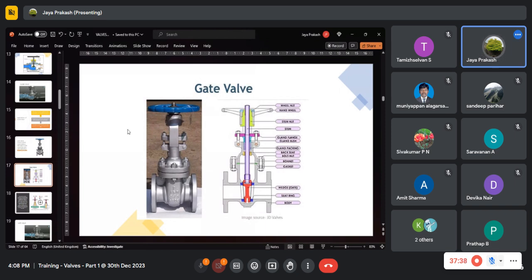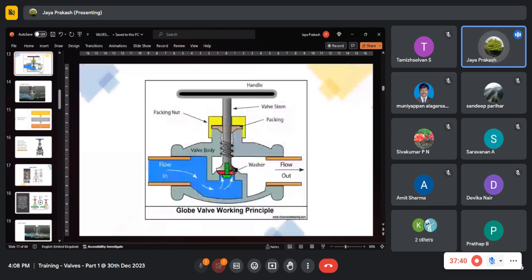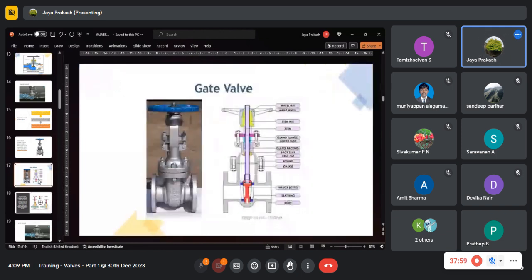They don't go for globe valve. See, globe valve will constrain the pressure, because the flow comes here, goes through this upward and goes again, because there are all these configurations, construction. This will automatically reduce the flow pressure. So that's why they don't go for globe valve when a steady flow of pressure is required. In those cases they'll go for gate valves.